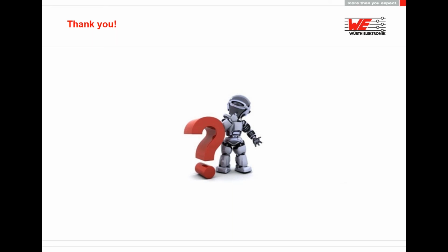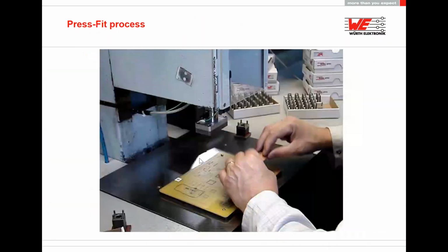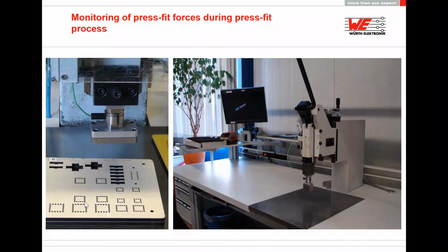Yes, maybe one thing I would like to add is regarding toolings, and especially for the matrix. You can also use it for prototyping, for example, because usually you need some tooling for prototyping, and for the stamp you can also use 3D printing if you have hard plastic. So you can make this matrix out of a 3D printer, and also the stamp, just for prototyping. It should be enough. But for series you need a very hard material.